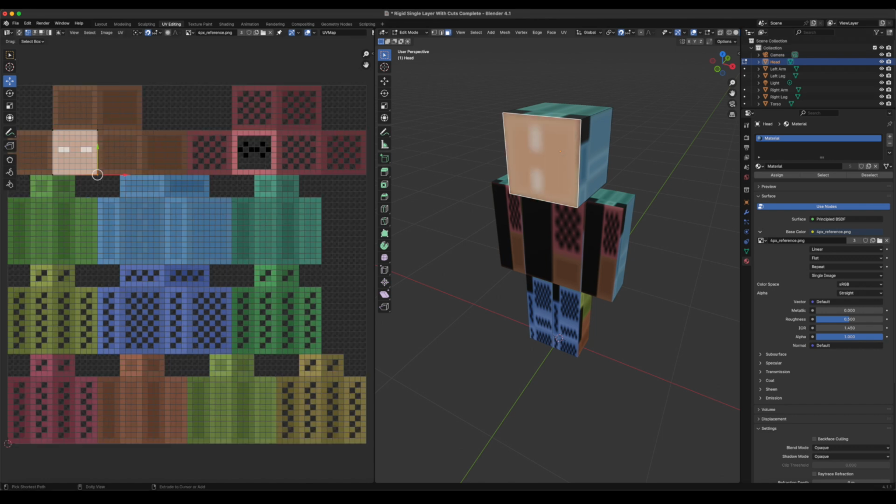There's a couple of ways to fix this. The first, and more complex method, which is recommended with more complex shapes being textured, is to directly move the UV island vertices to match those vertices on the model. In this instance, that would mean the top left UV island vertex would be moved to the bottom left position, since that is where that part of the image map is applied to the model, and so on.